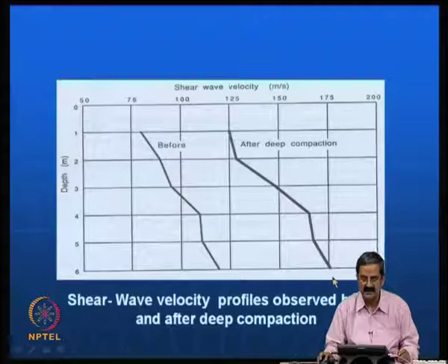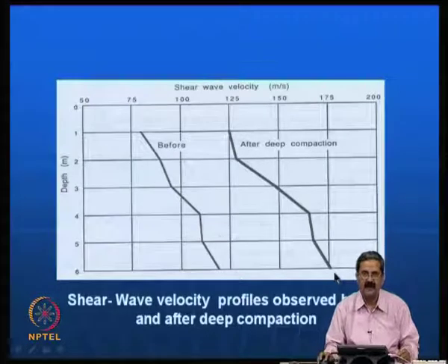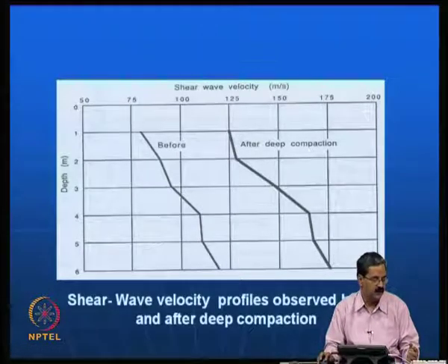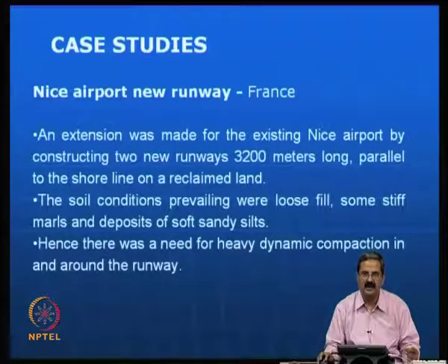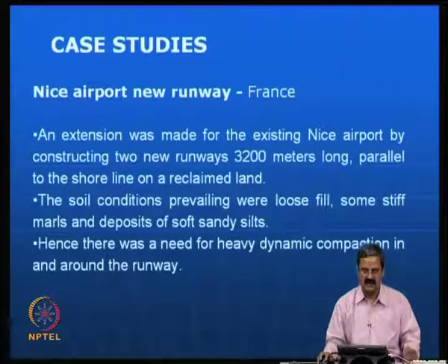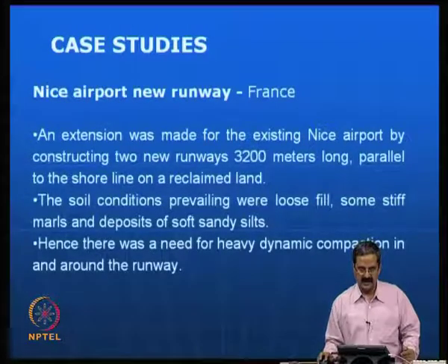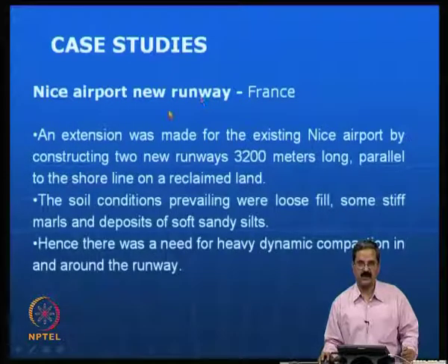So, what I mean is that some of these in situ techniques are very essential, particularly right from SPT value, cone penetration, pressure meter, then flat dilatometer and shear wave velocity measurements have been very effective in assessing the improved state of the ground. So, what I will do is I will just take you to a few case studies, because we have some case studies which are well documented.